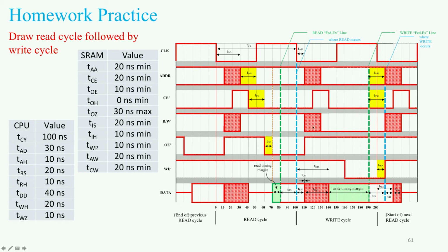Read-write has similar characteristics for timing, but since we're doing a write operation, the CPU is going to make this bit go low instead of being high. But the timing here, the 10 nanoseconds of hold followed by 20 of indeterminate, is the same, except that the value here is now going to be low.